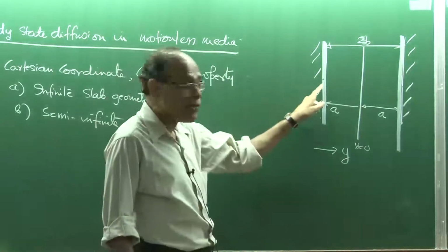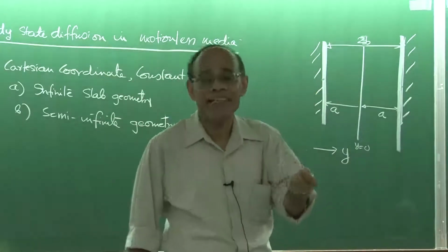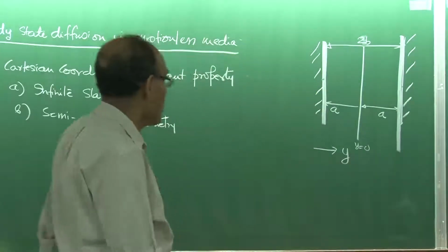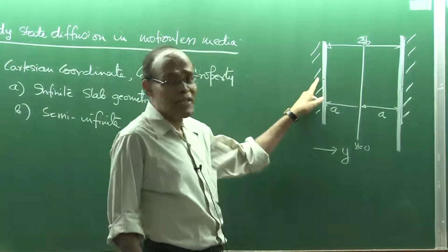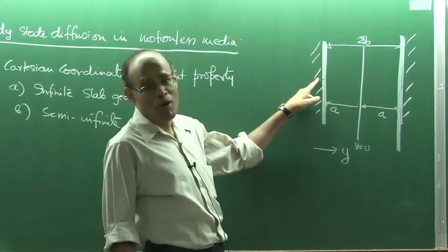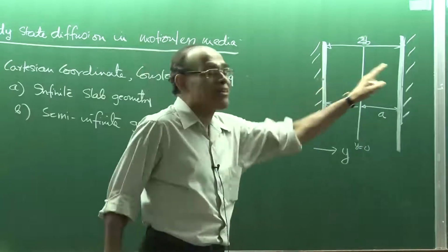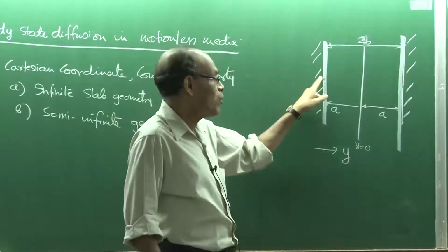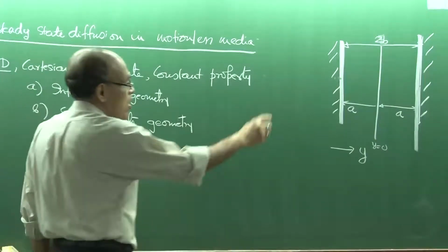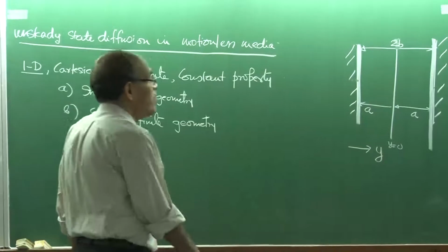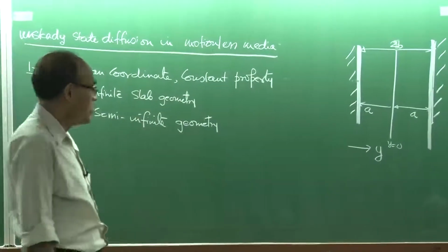In the context of heat transfer, we used a known temperature at the surface, and that temperature was an empirically determined temperature. So, through some devices we knew the temperature, and that is what we prescribed. And this temperature is a fixed temperature boundary, it is not a time dependent boundary condition that we have applied. So, for all time the temperature was maintained constant. Similarly here also, we will consider that for all time the surface concentration will be maintained at the same level. So, it is an isothermal scenario as far as mass transfer phenomena is concerned.